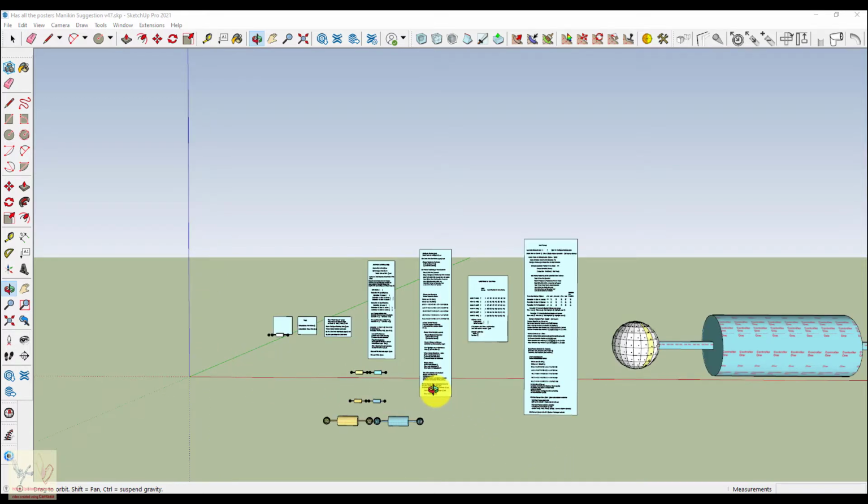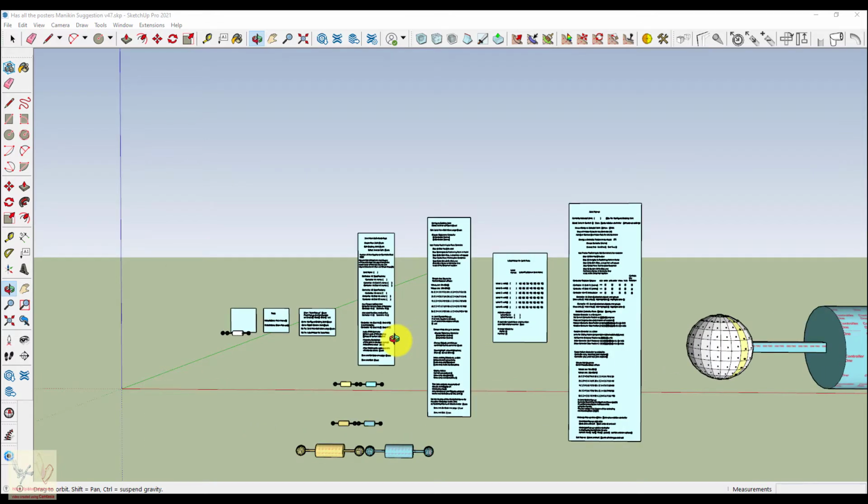This is going to be a system of restriction where, while there are thousands and thousands of different movements you can do, you're not going to be given permission to do any of these movements because you are using this articulation tool. So when you put the articulation tool in place and use it, it adds restrictions to how you can move around groups in SketchUp.